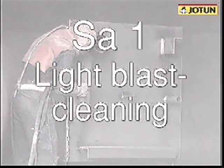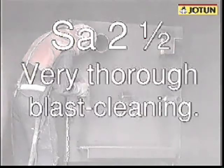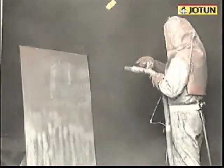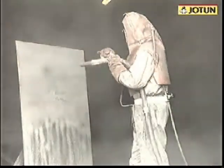The blasting standards are SA1, light blast cleaning, SA2, thorough blast cleaning, SA2.5, very thorough blast cleaning, and SA3, blast cleaning to visually clean steel. Light blast cleaning removes loose rust, paint and other foreign matter. Further blasting takes you through the different grades up to visually clean steel, SA3.